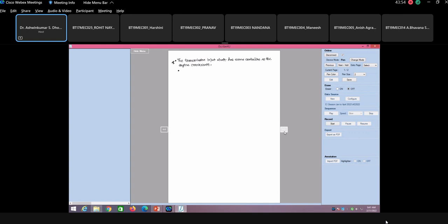So if a component is not designed for unknown loading, it will last till your factor of safety. After that it is going to break down, and you know that fatigue damage is cumulative. It is not that you are subjected once and it is over. No, it is cumulative. So damage accumulation happens, and if it happens, it is going to break. So we have to be very careful.